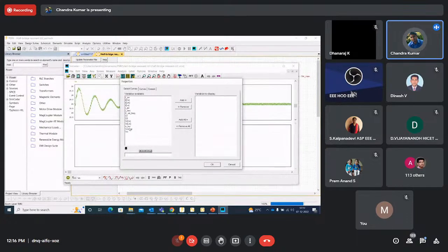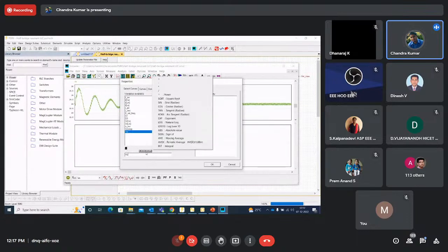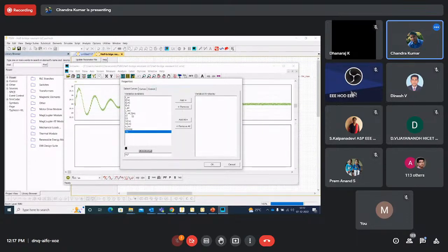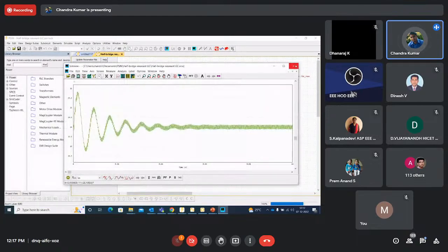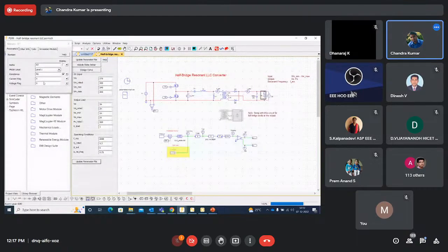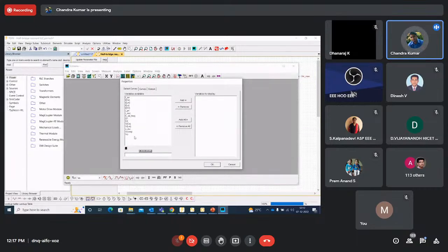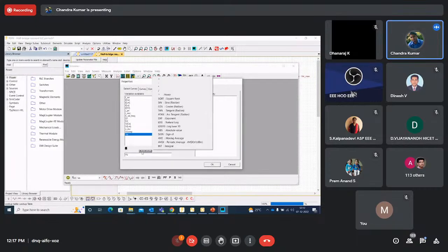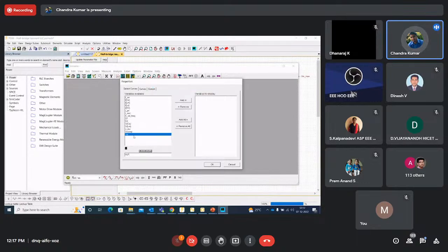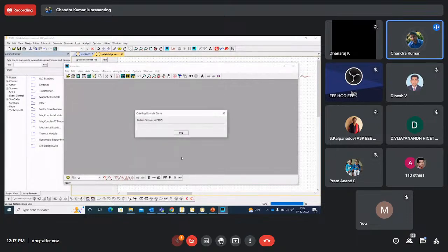And if you want to look at the power, I can add output voltage multiplied by current. I want to look at the current flowing through it. So let me run the current and enable this. I'll make this current flag 1. So I'll just run the model. Output power was 500 watts, so I'll add output voltage, multiply this, add my current IR7. Okay, add it.